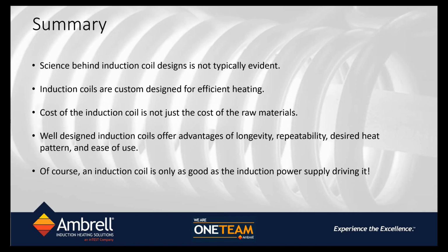So the critical piece of missing information is how long you have to heat the pipe. If you have, let's say, a minute to heat a 12-inch OD pipe, if I were to assume a half-inch wall or something, you could get it to that 2200, 2400 degrees temperature with about a 100 kilowatt power supply. So that'd be like a minute to 2 minutes type of heating process. Because the temperature is so high, you want to make sure that you have good radiation control, you have good insulation on the part.